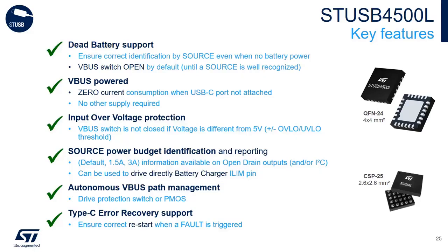In contrast, using a discrete implementation where a microcontroller must be powered up to negotiate the power contract, that means the protection switches are closed by default and opened only when a fault occurs. And it might close again outside of the USB-C negotiation, leading to interoperability issues.